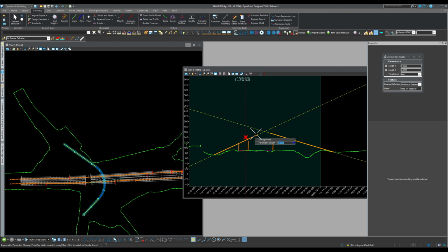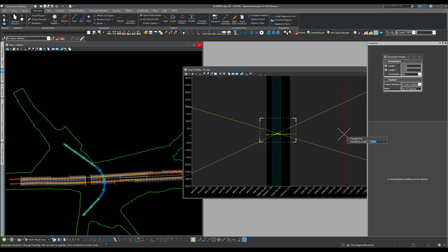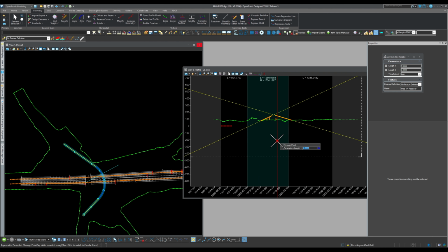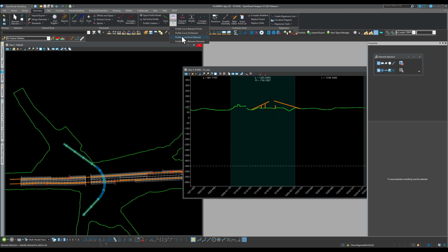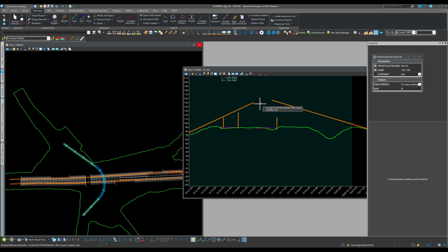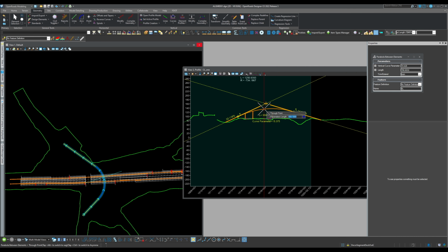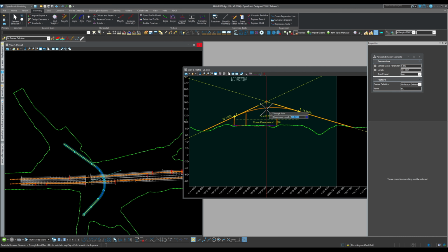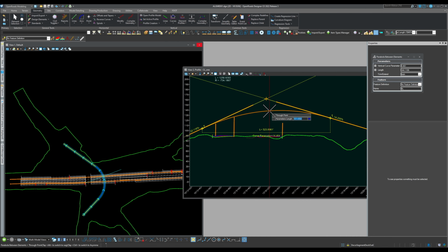It's just whatever you did here is not working, because the tool itself will go to the first element and the second element and then try to fill the equation between them. If it can't, you just get the red thing like this. That means it's not going to work. So let's try a basic one then. Parabola between things. So let's click on this one and then let's click on this one. So now this one seems like it works, and as you can see I can move up and down till how I want it to be.